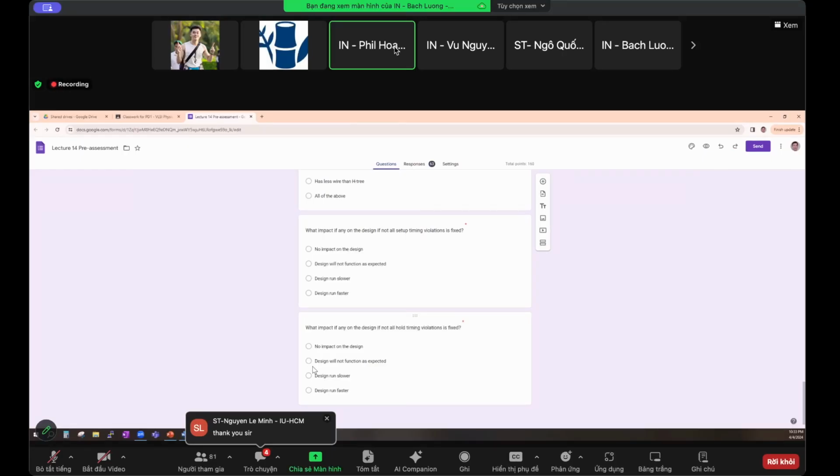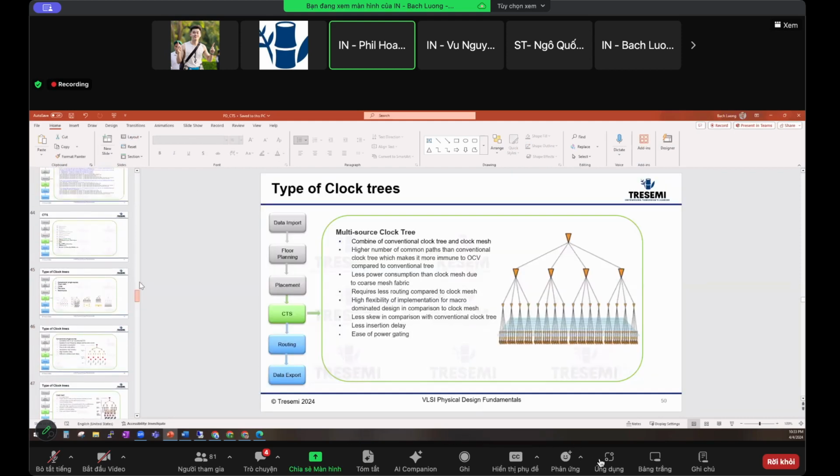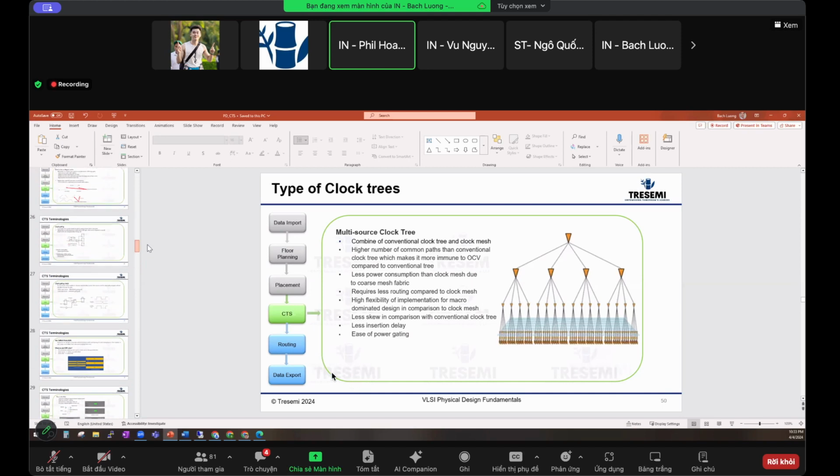I want to add two things to that. One is that slower means you have the chip back in the lab on an evaluation board, and if you run at speed and it doesn't run, you can lower the frequency of the input clock and it will run. But if you have hold time problems, no matter what you do with the frequency, it won't run accurately, because it has functional problems and is not speed dependent.